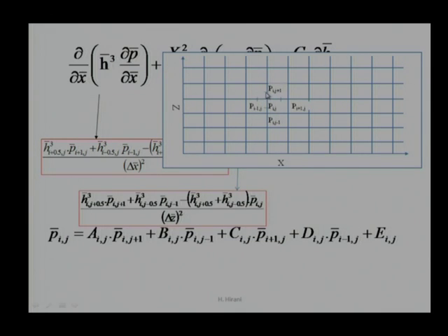And these are the half node points where we need to find out what will be the film thickness. As I say, the film thickness calculation is not a problem because it is geometry dependent, and geometry is given as a continuous function. We just need to substitute the value of x to find out what will be the h at that location. So, it is not difficult, it can be figured out, and once we find it, we do not have to do any iteration to vary those results. But pressure we need to find out, and that requires an iterative procedure.